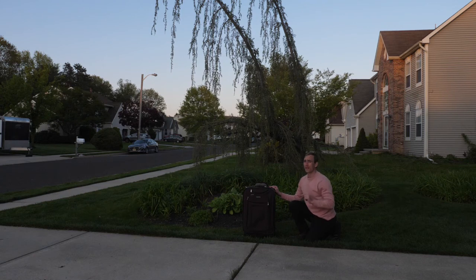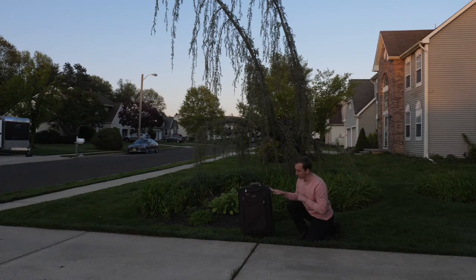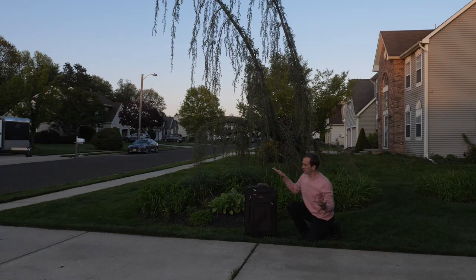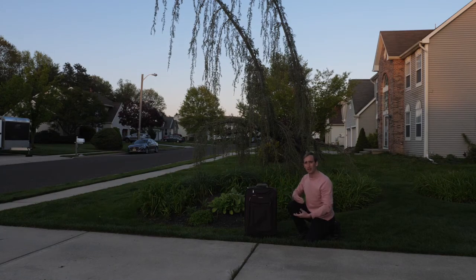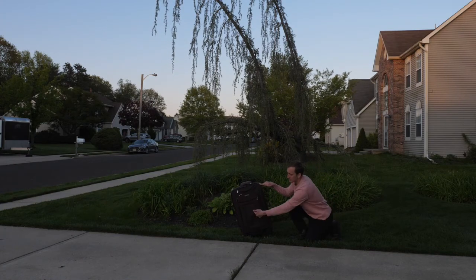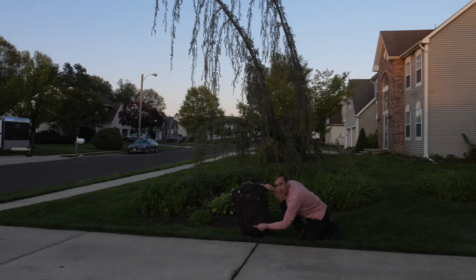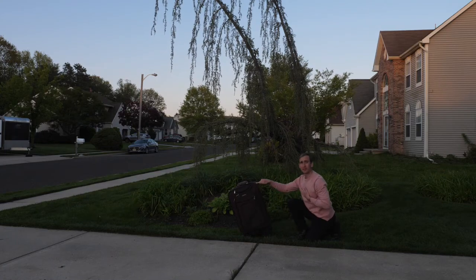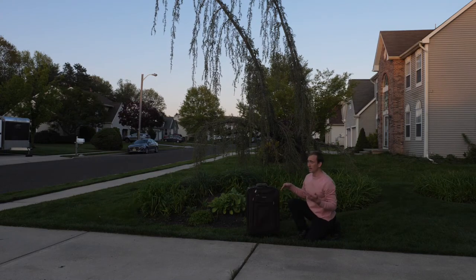There is one other factor that's going to matter. What we can see is that if our center of gravity is here, when I push on our bag, it begins to rotate. But when I let go of the bag, what happens? The bag corrects itself and rotates back towards me. The reason is that my force causes this bag to rotate counterclockwise, but the center of gravity is applying a moment relative to that wheel to cause it to rotate clockwise.